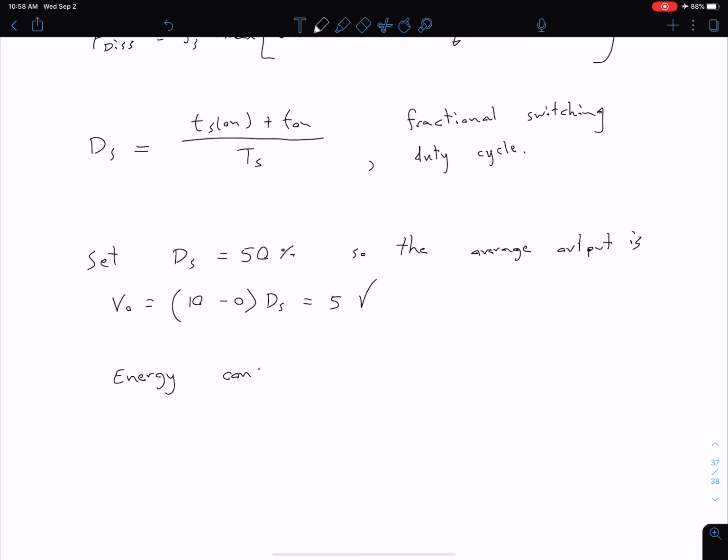And we're going to use this principle to determine our maximum load current. So we want to find the current during the on period, which is going to correspond to our I max. We can see that in some of the plots that we had in a previous video.